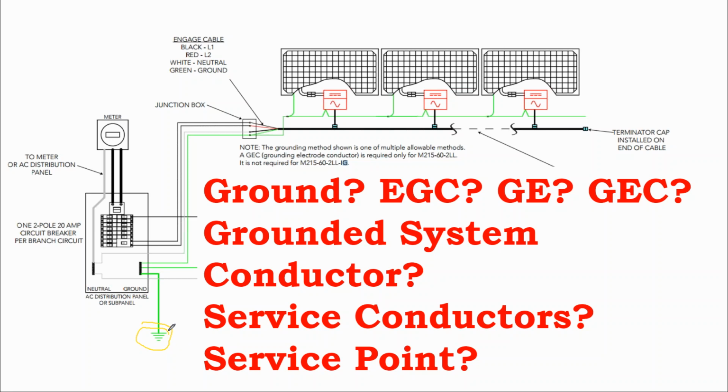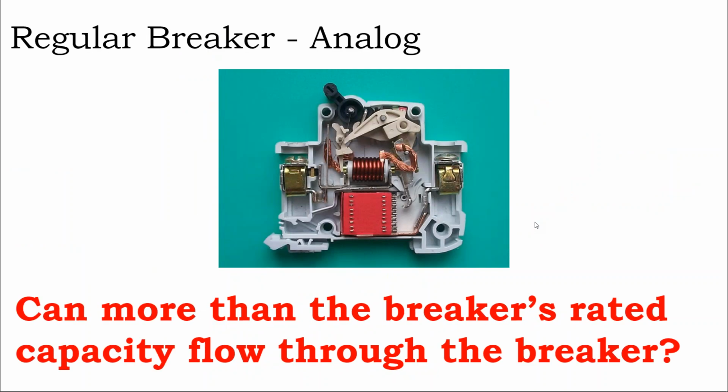We're going to talk about that in a minute. A ground rod, a ground plate, a whole bunch of copper wire thrown into the ground. Whatever your grounding electrode technique is, there's a few of them. There's a special term for the very last ground in the chain, which is the grounding electrode conductor. Sometimes that needs to be a little bit larger: a 400 amp service needs a larger one than a 200 amp service. So keep that in mind.